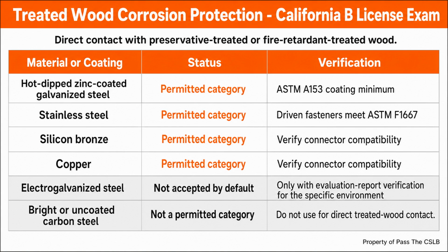The single idea tying all 4 together is system, not part. The metal connector is only one part of a tested load path. The exact fasteners transfer the force. The wood receives it. The corrosion protection preserves the connection. The instructions define the configuration that earned the published capacity.